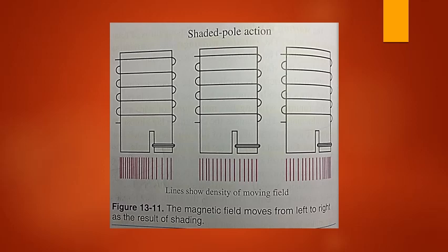At the top of the AC wave, very little current change occurs. The total magnetic field becomes equalized across the face of the pole. When the current starts to decrease in the next quarter cycle, the polarity of the induced current in the shading coil resists the decreasing current. So the pole has a strong magnetic field on the right side.